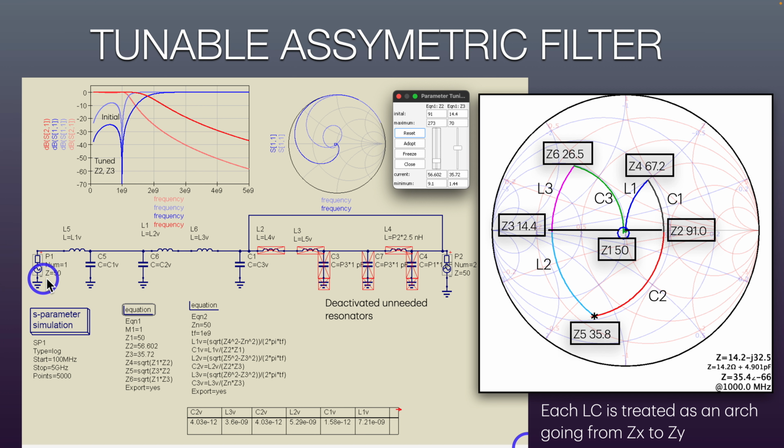And so in this case, I've got two capacitors here. Those later would be lumped into one capacitor, but we've broken them up for the purposes of doing these calculations into two. The same goes for these inductors. These will be combined later, but for right now they're being treated as two. So I get this LC pair, that LC pair, and the final LC pair, and run through these calculations using the impedances to get the LC pairs at each jump in this trace.